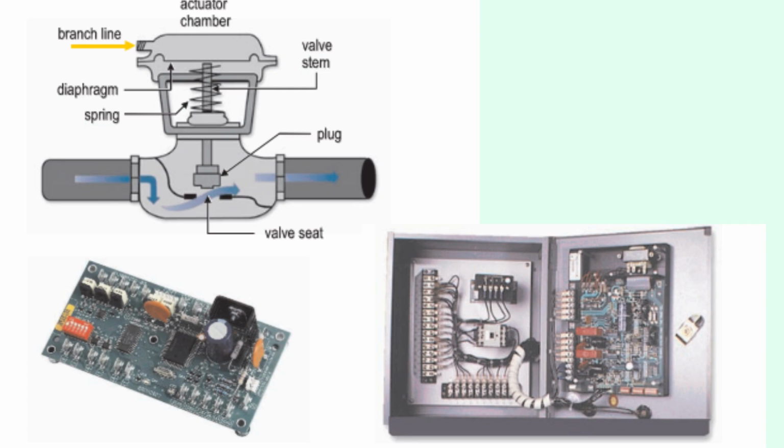Controller technologies. There are 3 main types of HVAC controllers. Pneumatic systems use compressed air to move valves and dampers. Old school, durable, but high maintenance. Analog electric controls use electrical signals, faster and cleaner but less flexible.